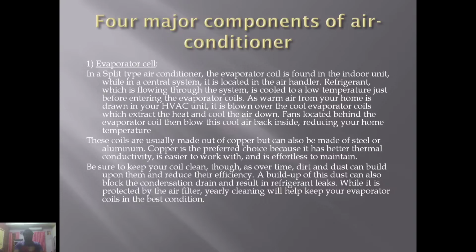Be sure to keep your coil clean because as time passes, dust and dirt can build up on them and it will affect the efficiency of the coil. A build-up of this dust can also block the condensation drain and result in refrigerant leaks. While it is protected by the air filter, yearly cleaning will keep your evaporator coil in the best condition.